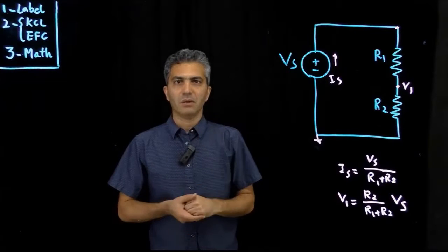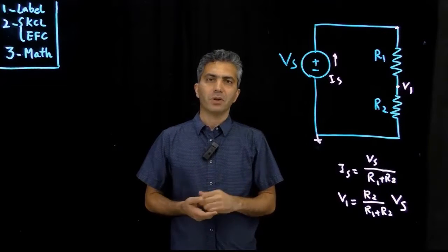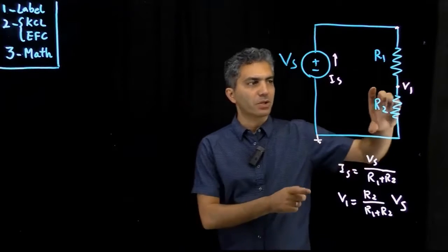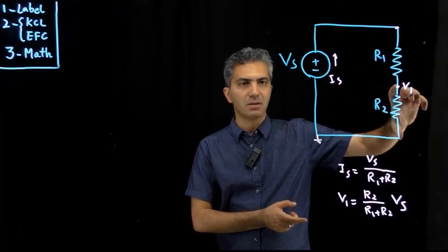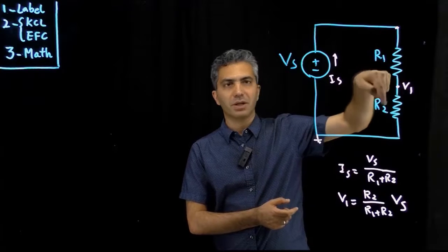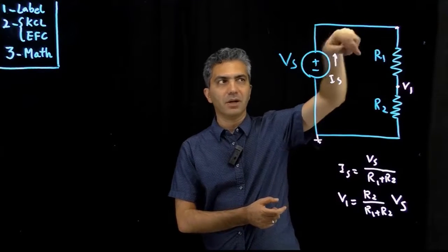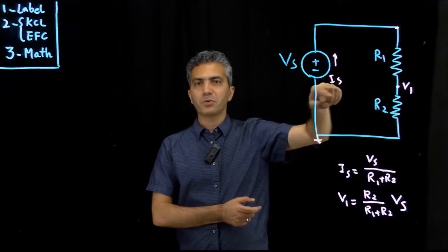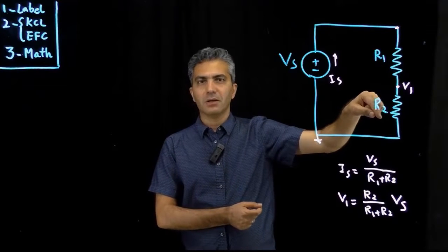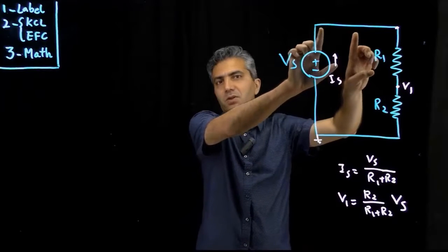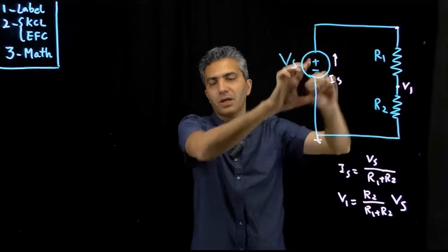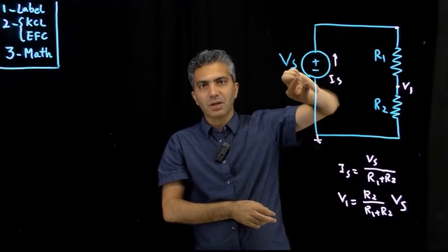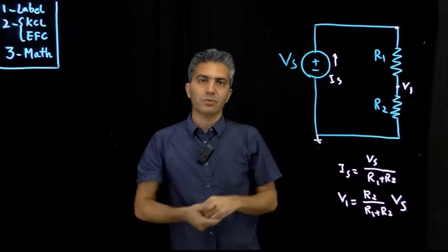And you have to be mindful of how to use these terms properly. So when you measure a voltage, the voltage is across two terminals, but when you're measuring a current, usually you have to open up the path through which the current was originally going, and then from the two connections that are a result of opening up your circuit, put your ammeter in and measure the current that is going through those two terminals.